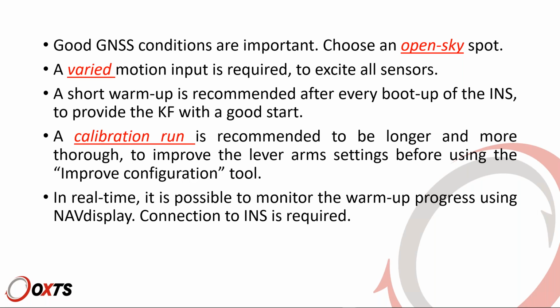If you are doing a calibration run, take your time, do at least 5 minutes, 10 minutes even better, because you need to remember that you will use this configuration time and again. So you only bother once to do this thorough warm-up to improve your configuration. You save it on the system, and from that time on, you just need to do short warm-ups of a couple of minutes.